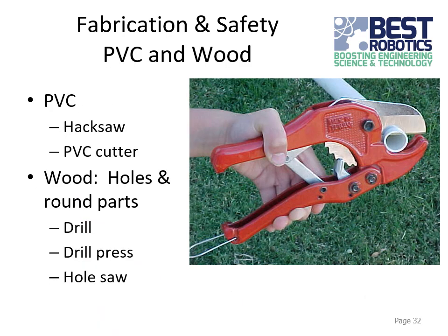Okay, so for PVC pipe, you can, of course, use a hacksaw to cut that. That's what I personally use whenever I need to cut PVC. And that can do a pretty good job of getting you a nice clean cut on the PVC. They also make these things called PVC cutters, shown in the picture there. Those are designed for cutting PVC, and they're super quick and easy to use. Sometimes they can make the edges a little rough, and the hacksaw can do that too sometimes.